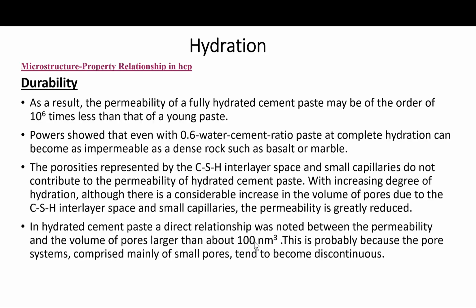As a result, the permeability of the hydrated cement paste may be on the order of 10 to the power 6 times less than that of a young paste. That's how much full hydration does for us.